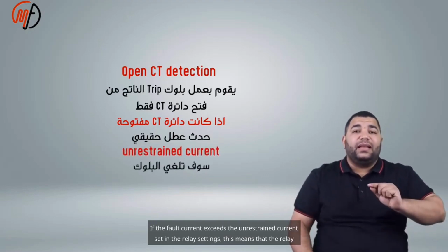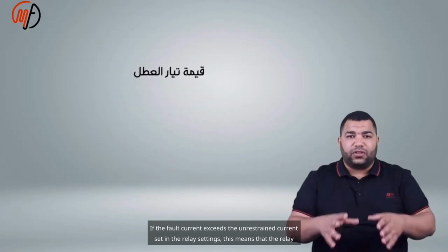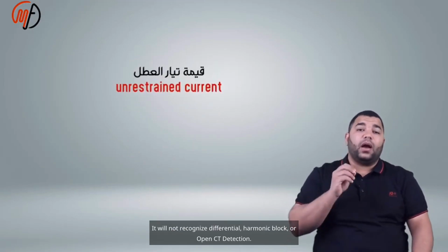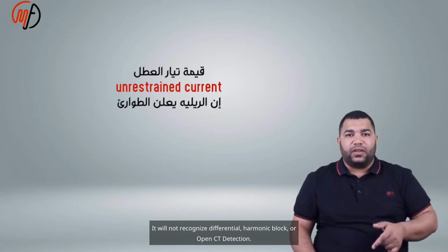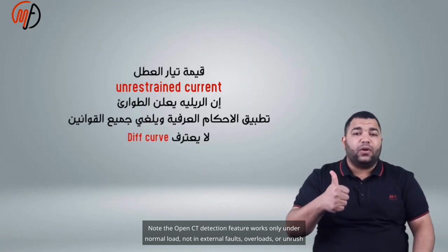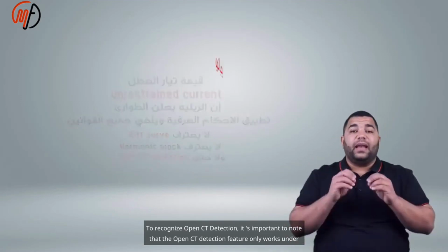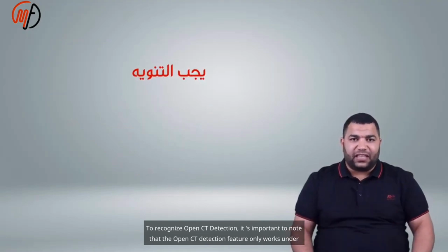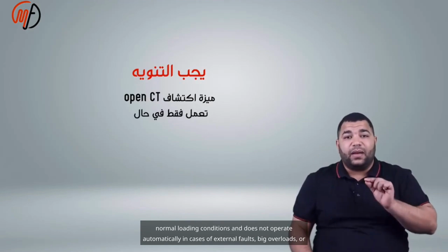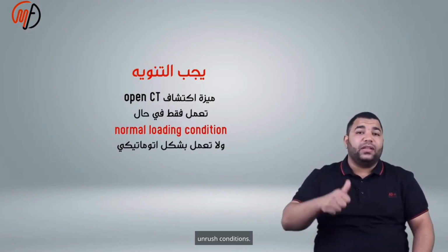If the fault current exceeds the unrestrained current set in the relay settings, this means that the relay has declared an emergency, ignoring rules. It will not recognize differential, harmonic block, or open CT detection. Note that the open CT detection feature works only under normal loading conditions and does not operate in cases of external faults, big overloads, or inrush conditions.